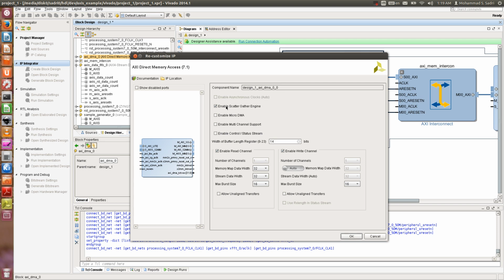In fact, you define the set of transfer tasks for the DMA engine and you put them somewhere in the memory, and as the DMA engine accomplishes one transfer task, it automatically proceeds to the next transfer task and so on. And it doesn't disturb the CPU at all.